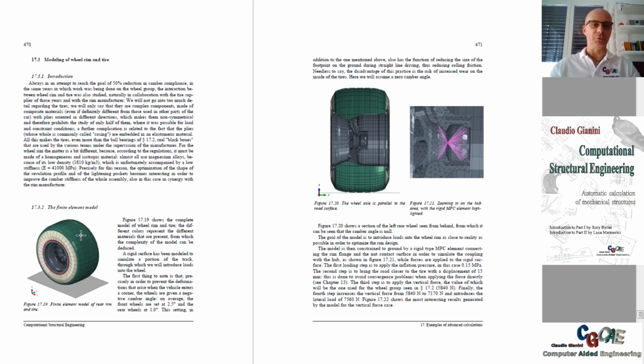The idea was to have three load cases: pressure inside, then pressed on the road, which is shown here on the track, plus then adding a lateral force, with the forces coming from the telemetry data on one of the most loaded corners, fast corners.